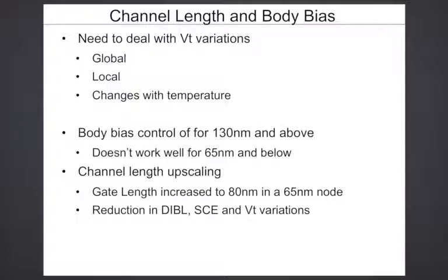The other problem of increasing the channel length is that your speed will come down, because the whole point of scaling is to reduce the channel length and get speed, but by increasing the channel length, you are compromising on the speed. Now, when you have paths which are not critical in terms of speed, you can definitely do this. And also for sub-threshold, near-threshold computing, where we are anyway targeting not very high performance, right? Low to medium performance devices. Increasing the channel length might be a good strategy.